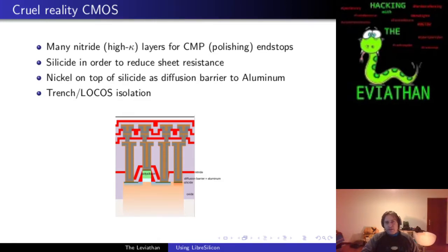You will always have to compensate for the change in topology by using planarization. More specifically, chemical-mechanical planarization, also known simply as polishing, where you take the wafer with the oxide, with the bumps, and basically sandpaper away the bumps in order to avoid irreversible crystal damage on your silicon wafer, or with the metal interconnects, damage to the wires.